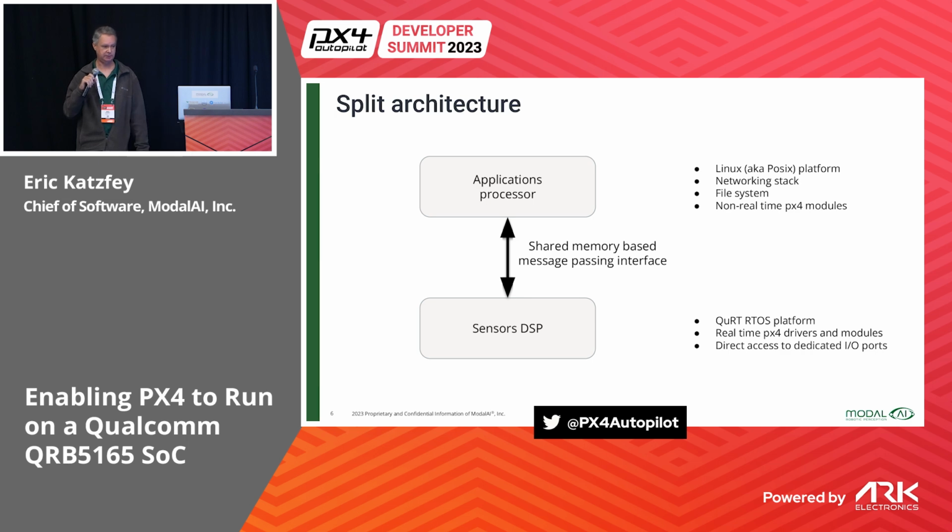The one that we utilize for PX4 is called the sensors DSP, which is really handy because it's got a lot of I/O routed to it. Obviously, for a drone, you need external I/O, I2C, SPI, UART, these kinds of things. It's got that directly routed into this DSP. So it made a very handy home for running the PX4 flight critical tasks.